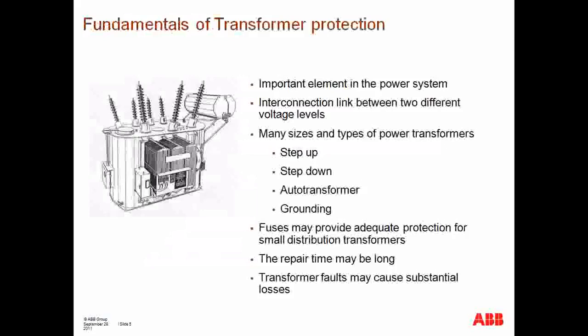As most of you know, the power transformer is a very key and important element within the power system. Essentially, power transformers enable more efficient transfer of bulk power. Within the context of this presentation, one of the basic functions of the power transformer is to step up voltage to a level high enough that you can carry more real power flow through a particular corridor without having to send as much current as you otherwise would with a lower voltage. That allows us to reduce our resistive losses over that particular transmission line.